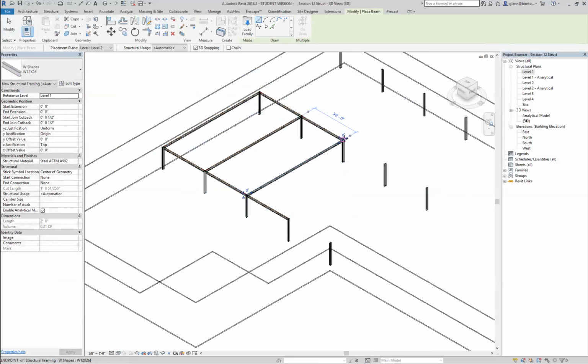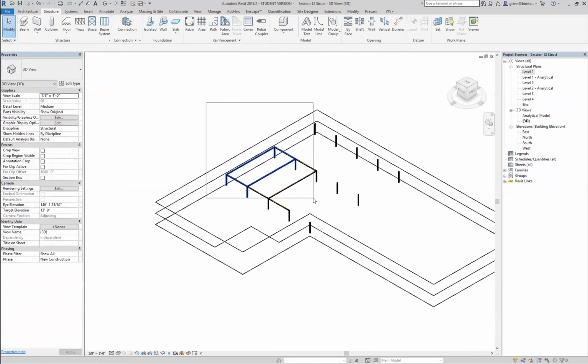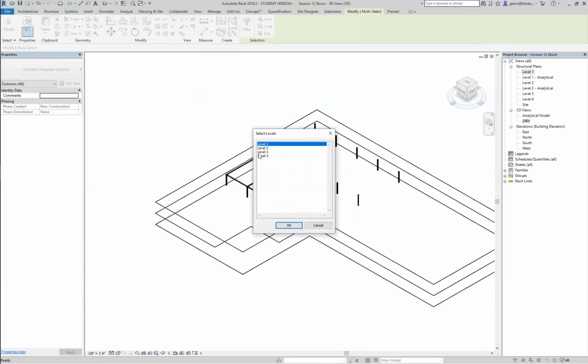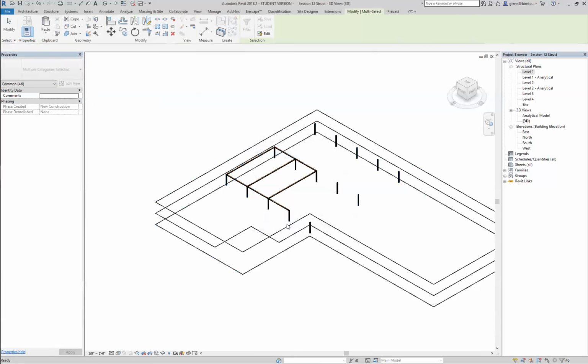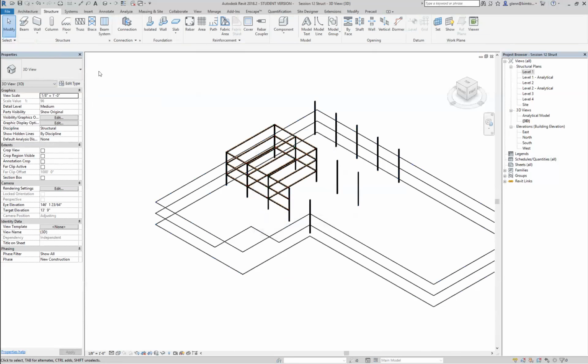And what we're going to find out is that our structural engineers like to copy and paste just as much as our architects do because it helps them too. So I can say, let's copy. I'm going to grab all those columns and beams, copy them to the clipboard, and paste them to levels 2 and 3. Actually, 3 and 4. Structural engineers have a different view of the world, so they think all those beams and columns are on level 2. So it's going to be on levels 3 and 4. Okay, let's save that away.